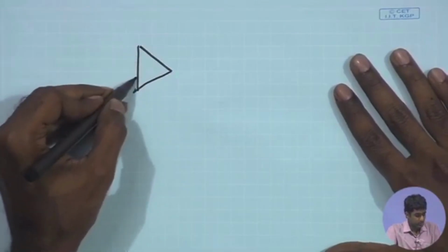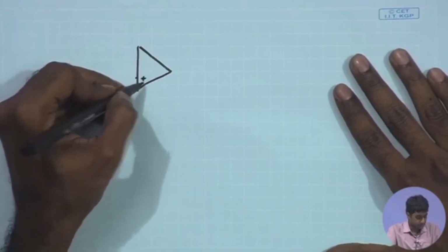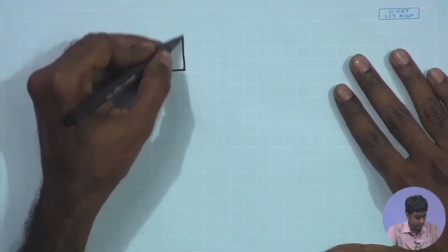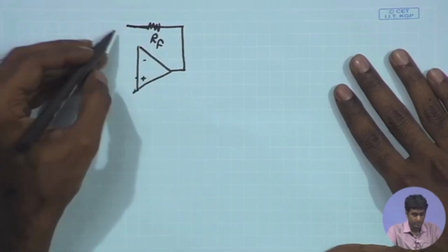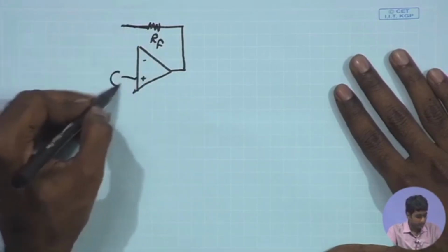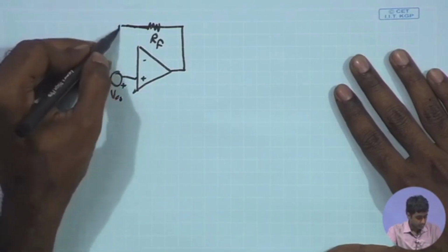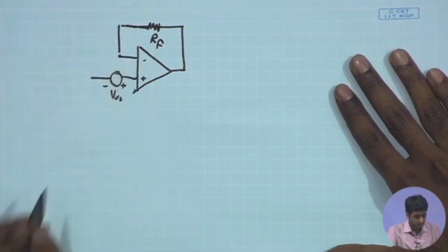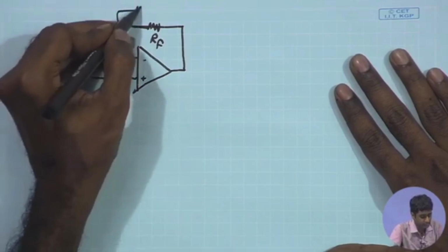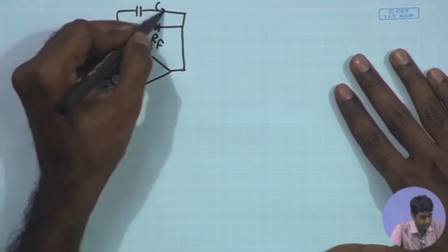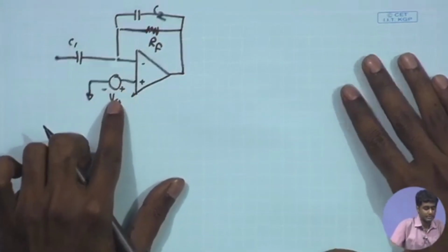So, let us look at the single ended version. You have a large resistor RF that we saw in our example connected over here, and you have the V offset, plus minus, and you have negative feedback, and then of course you have the capacitors which are implementing the gain, C1, C2, and on the other side, suppose you have a DC potential.